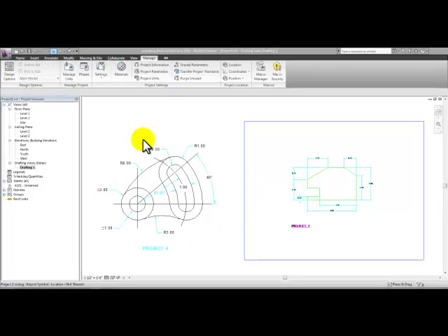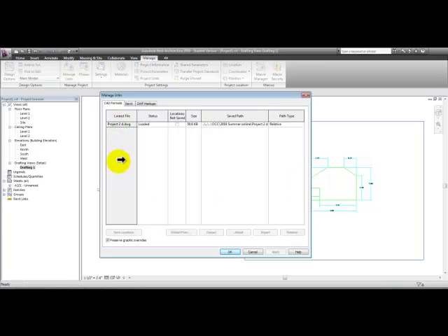One last thing, as an overview of working with linked or imported files, is in the Manage tab under Manage Links. You'll have several links here. Those are the files that are linked to your Revit file. The status is if it's found or not found. When you link a CAD file to Revit, it's looking for that file in that specific spot. If someone deletes or moves the file, then the status may say not found.